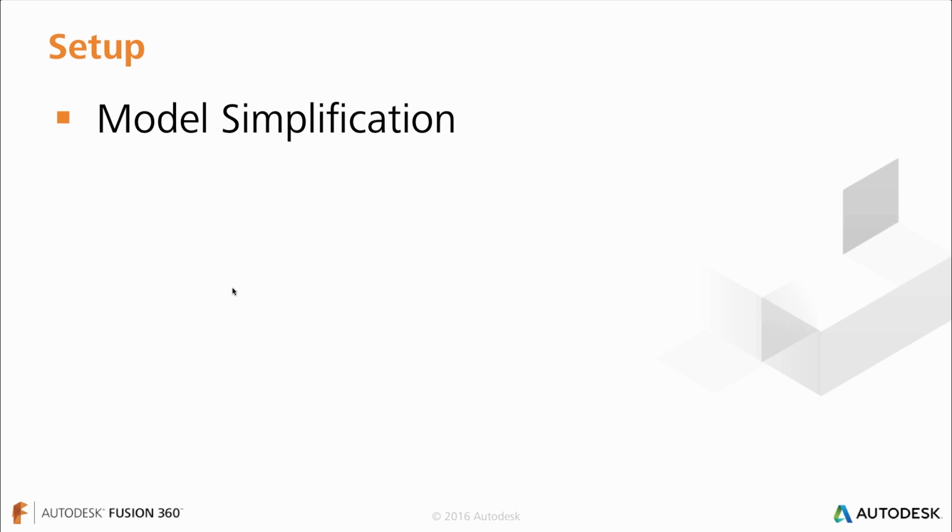I'm going to jump back into Fusion and actually start working on this model. So, simplify the model or geometry that you're going to be using for the simulation front of the design. Next is material definitions. What is the material that you're working with? Is the material that we're using from our database, is that accurate to what you're actually using? You might have different details.